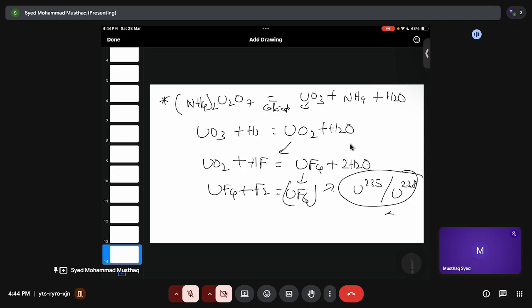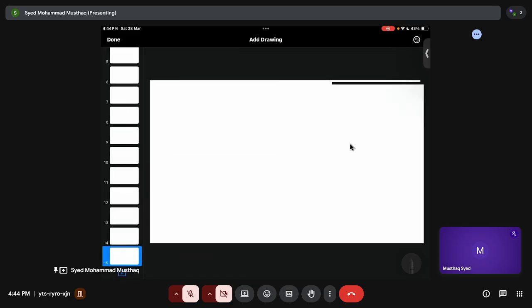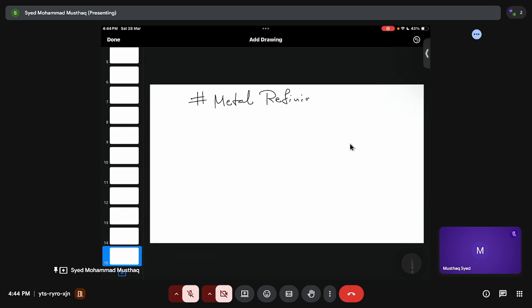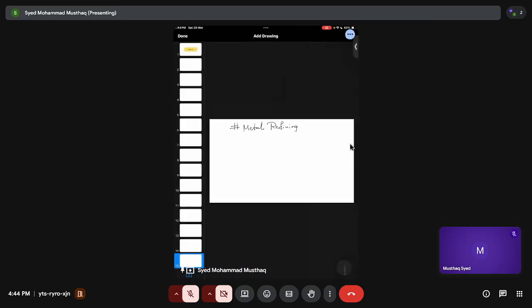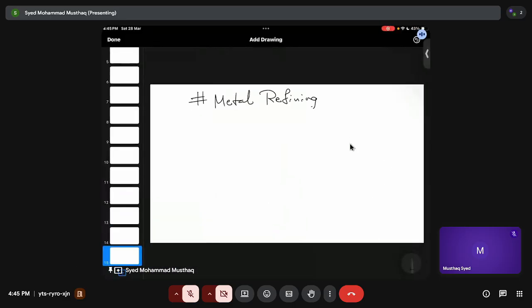See, people who are familiar with statistical entropy, not metallurgy, can relate to this. In statistical mechanics, when you try to prove the statistical entropy, you will end up with this relation: delta S equals minus (xa ln xa plus xb ln xb). And what are these? This is the mole fraction of A atoms and the mole fraction of B atoms. And what is delta G?